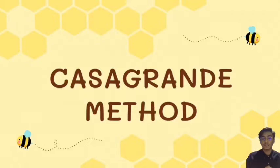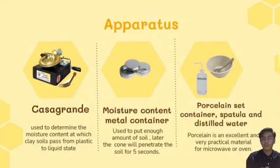Apparatus for the Casagrande method. The first one is the Casagrande device, used to determine the moisture content at which clay passes from the plastic to the liquid stage. The second one is a moisture content metal container, used to hold enough amount of soil. Later, the cone will penetrate the soil for 5 seconds. The third one is porcelain dishes, containers, spatula and distilled water. Porcelain is an excellent and very practical material for microwave or ovens.